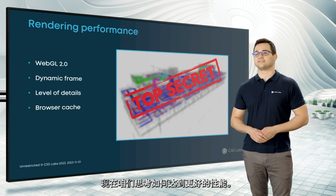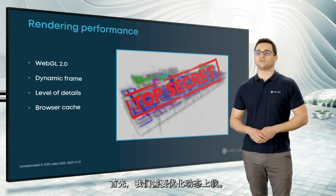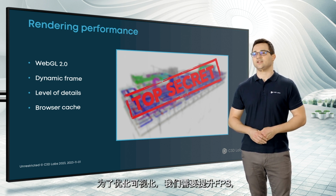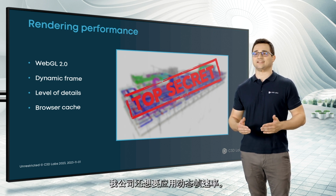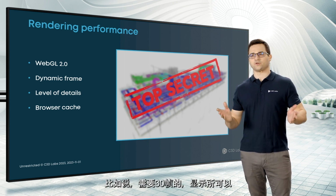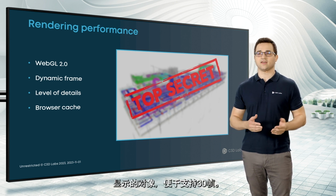And now let's consider how we want to achieve better performance. First of all, we want to improve our dynamic loading. To improve visualization, we need to increase FPS and move to WebGL 2.0 to take advantage of its new graphics features. Also, we want to use a dynamic frame. It's when the rendering of the model is adjusted to the number of frames. For example, you want to see 30 frames, and we will draw as many objects as we can to keep 30 frames.